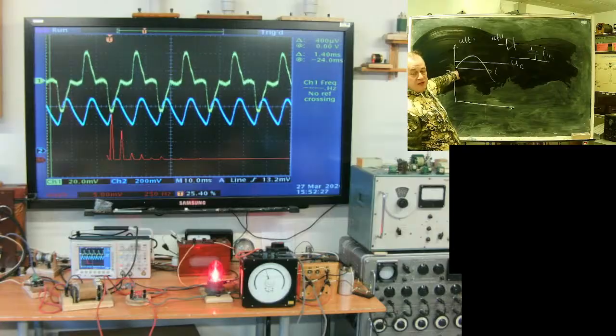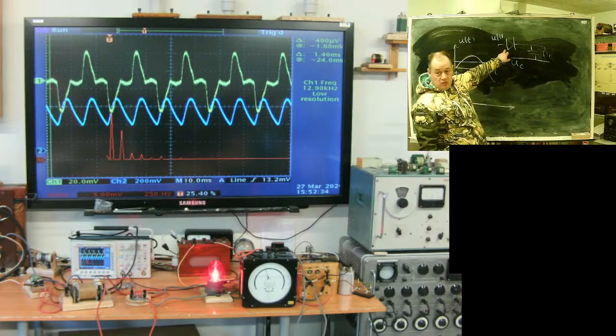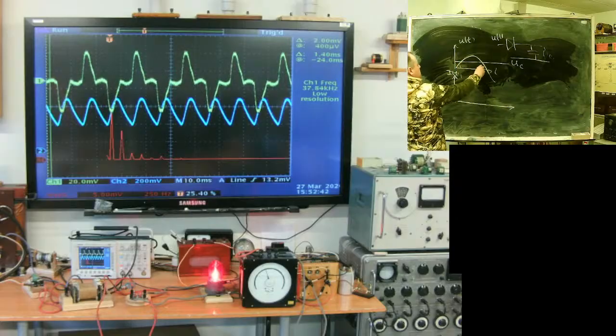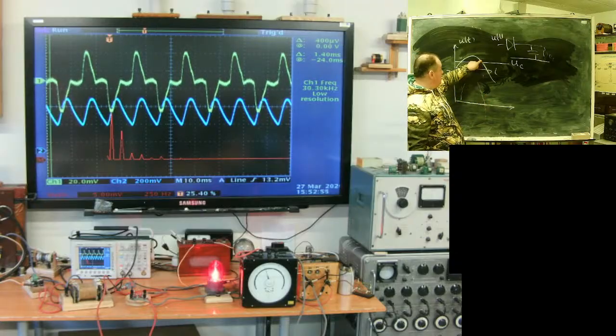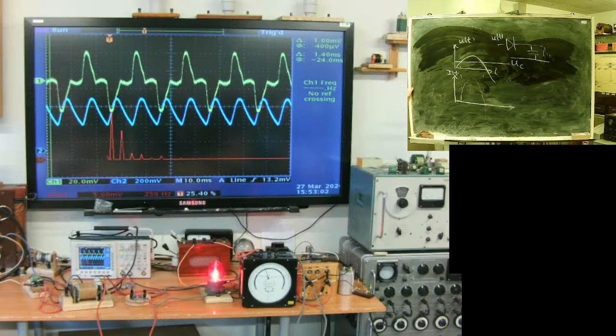Before the net voltage is above the capacitor charge, no current flows because the load is closed. Zero. Then, starting from this point and up to this point, the current will be something like a sine pulse. And again, zero. Short pulses charging my capacitor.